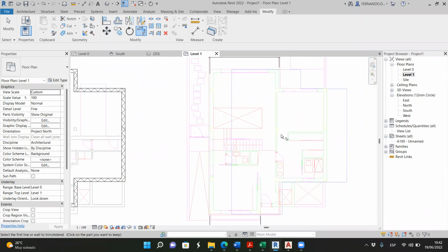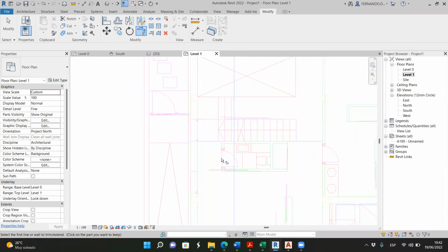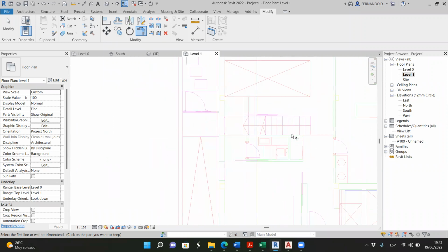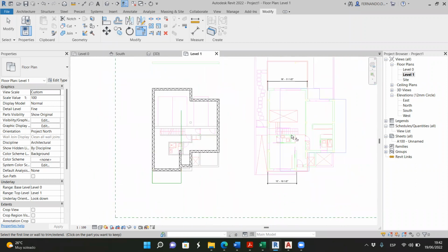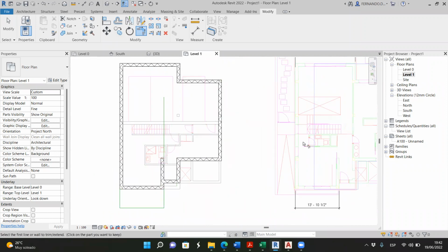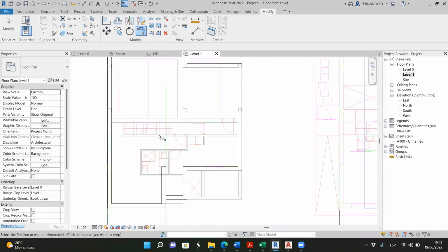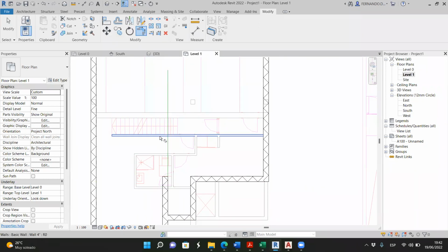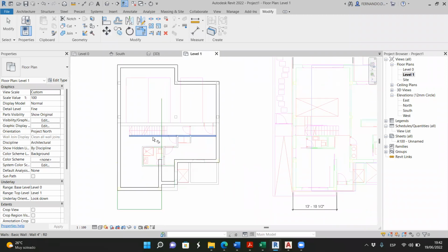Now we have to do the internal walls, interior partitions. Well, interior partitions don't have to be aligned or lined up from the basement because the structural elements are the thick walls. Those thin walls, they don't have to match. Usually they do.